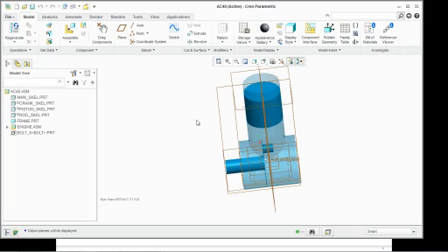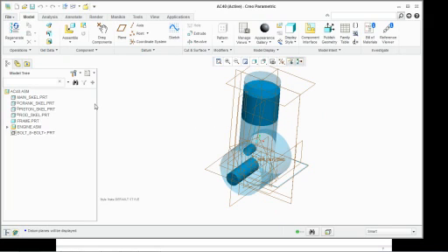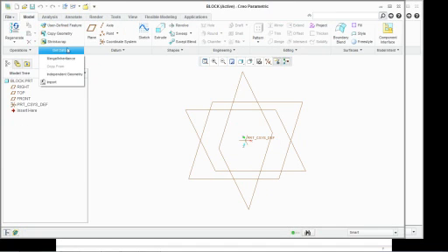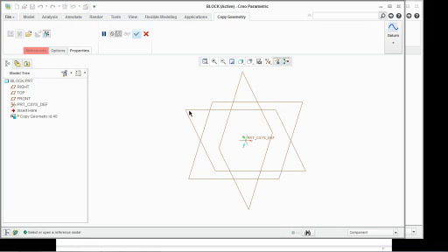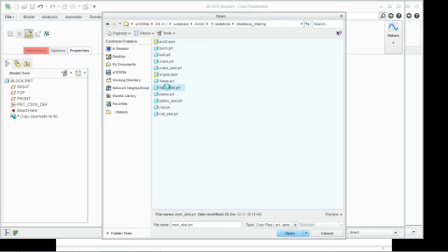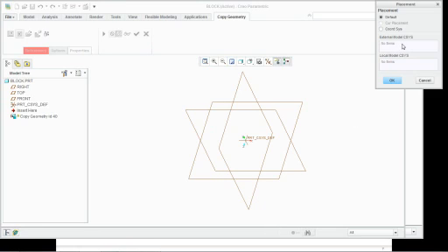So I'm first going to open up this first engine block, and I'm going to say I want to get data. I want to go copy geometry, and excuse me, click open. I want to turn off the published geometry only. I'm going to click open, and for the block here I want to select main skeleton, and in here I need to select which coordinate systems I want.